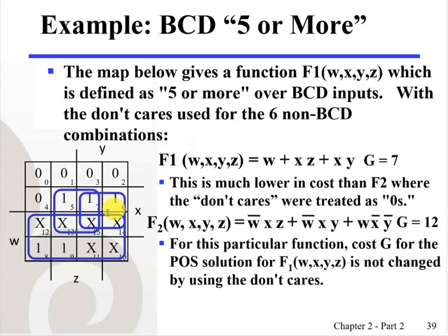So don't cares allow us to form larger groups of ones in the K-map. The locations of these cells are again the output values of the function. If you think of this as a truth table, the BCD function, whatever is above 9, such as 10, 11, up to 15, will not be considered in BCD. But we can use those values in our K-map.